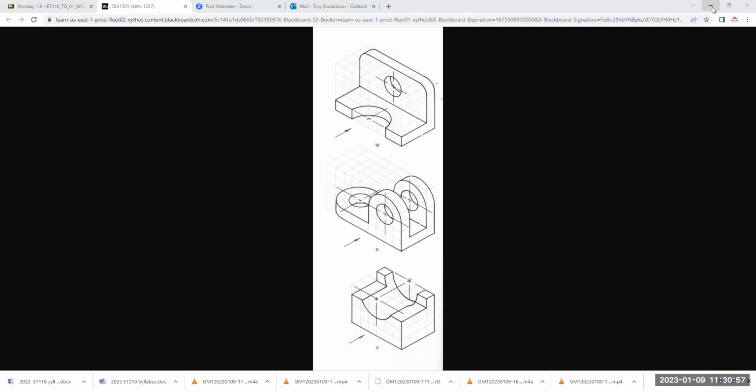And you want it to look like the dimension style that you want it to look like. Not, this is AutoCAD's default for US inches. So first thing is accuracy. We don't want 4 places. Is that 4 or 3? Yeah, it's 4 places. However many places we want, right? Or if we want fractional, then we have to change it, right? Arrowheads are good. We want those. We do want annotative. Annotative means it's going to scale it for us, so we don't have to think about it. Okay, so we want annotative dimensions.